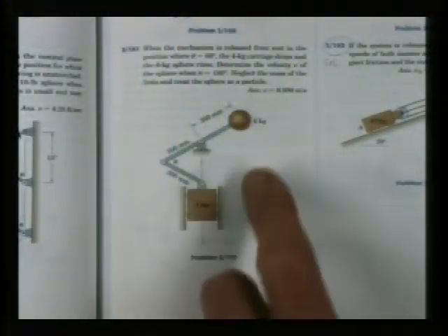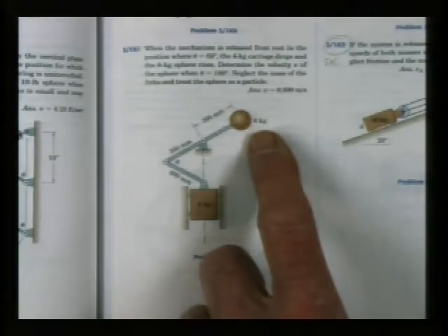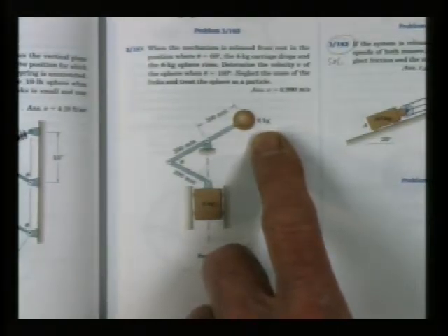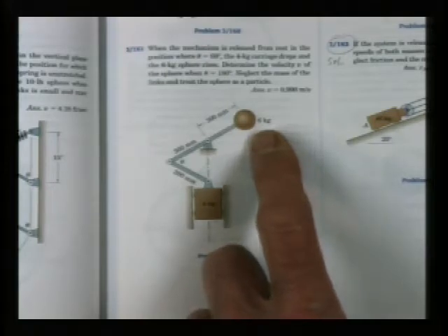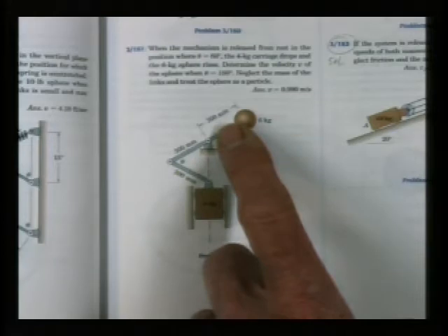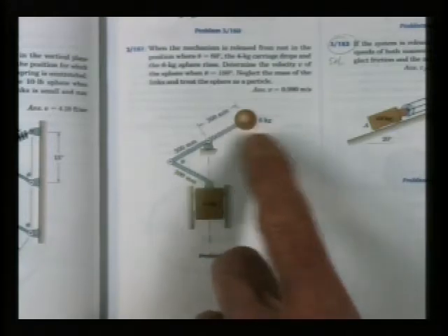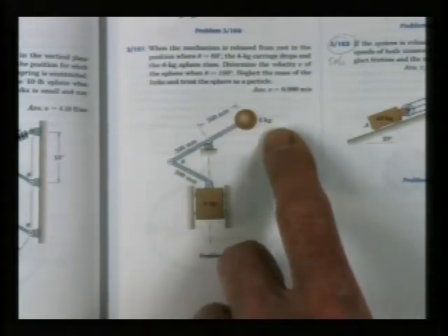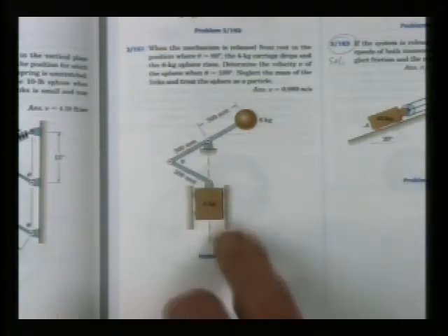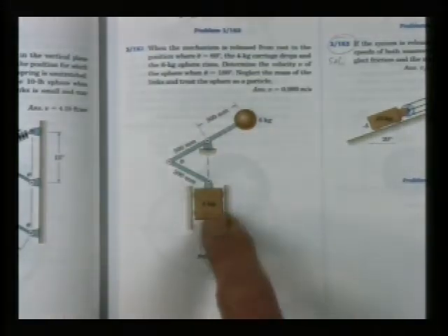using the work equals change in energy, where there's some rotation involved, which is similar to what you have assigned in a few problems. So here's a mechanism pinned at this location on a 300 millimeter arm, roughly close to 1/3 of a meter in length, and a 6 kilogram mass out there. And then hinged to that is this 4 kilogram mass, which can move up and down in this frictionless slot.